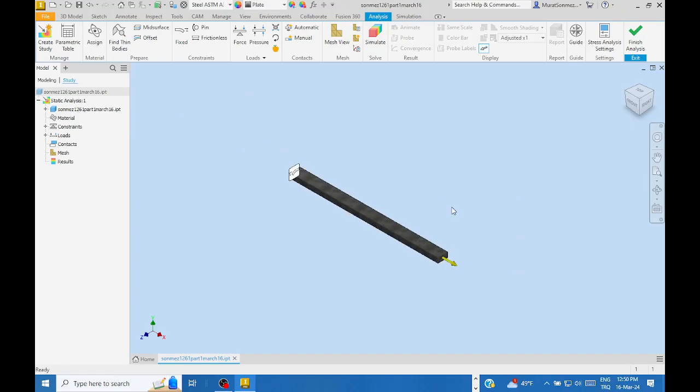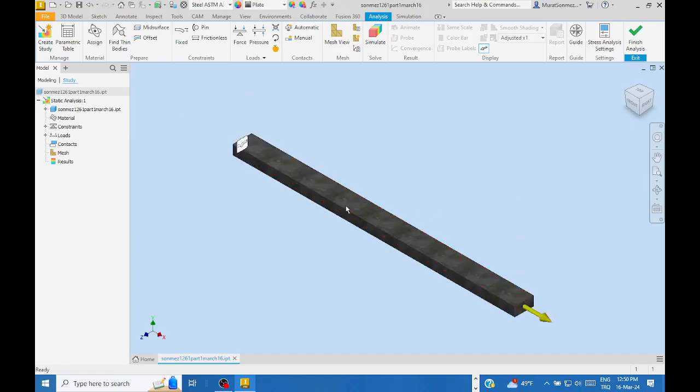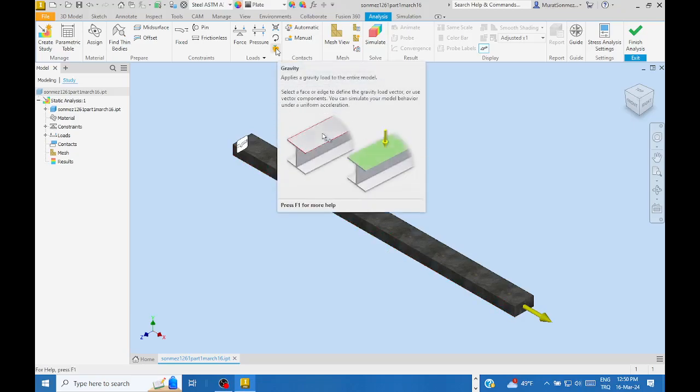How about the gravity force? If you calculate the weight of this object, then relative to 80,000 newtons, you can conclude that it is negligible. If you say that it's a massive, bulky object, then its weight is quite effective for the reaction forces and also the atomic bonding forces. Then the answer is to click on this button and teach the software which side the Earth is. Okay?